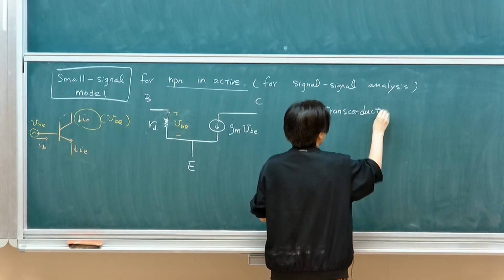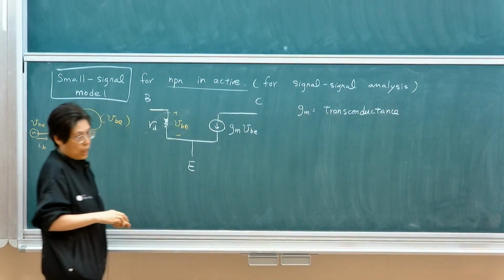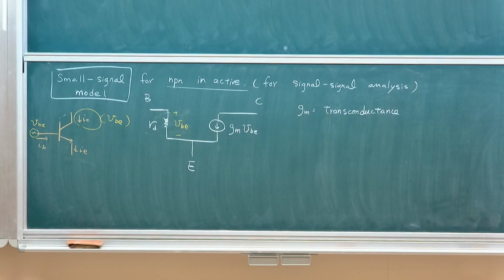We're going to talk about the meaning of this transconductance. gm is one of the key parameters if you're doing device design or you're a technology developer. What you need to deliver, one of the key parameters, is gm, transconductance. It tells how much the output changes for a given input change. So this is the sensitivity of your transistor.